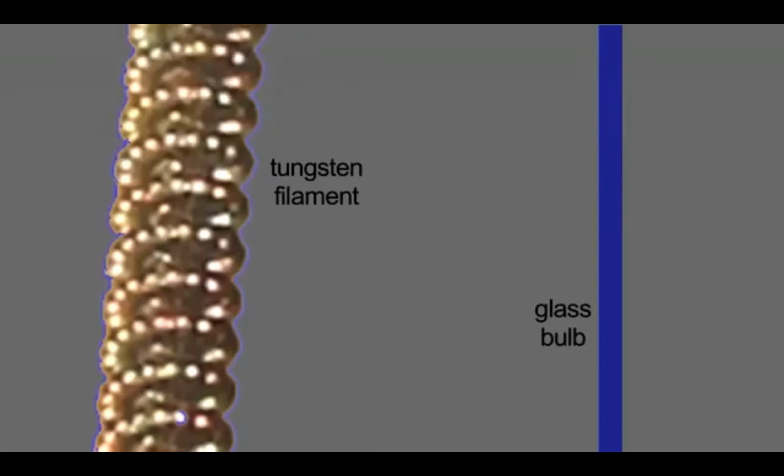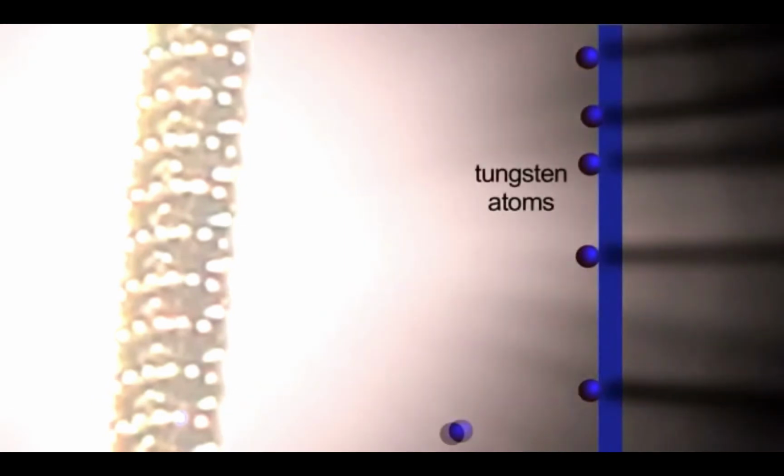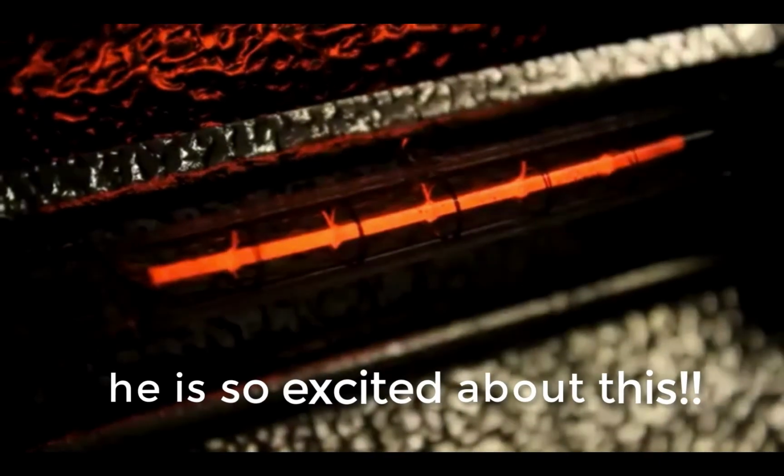When the filament operates, tungsten atoms will evaporate off of the filament and deposit on the inside of the bulb, and it'll cause the bulb to blacken over time, which is familiar with ordinary incandescents. Halogens don't usually blacken much, if at all, because when the atoms come off of the filament, they unite chemically with the halogen, and when the halogen cools, the chemical compound changes yet again and actually redeposits the tungsten atoms right back on the filament again.